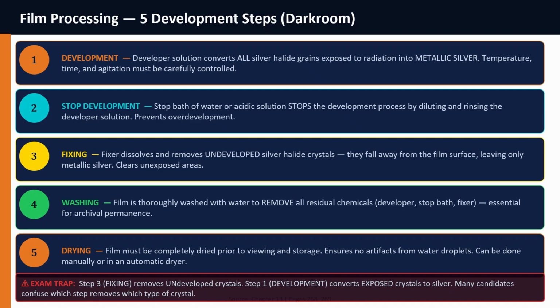Insufficient washing can leave chemicals that degrade the film over time. So film processing is not simply a laboratory procedure. It is part of radiographic quality control. A technically excellent exposure can still produce a poor radiograph if the film processing procedure is poorly controlled.